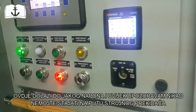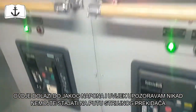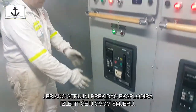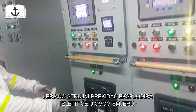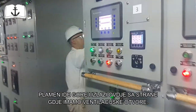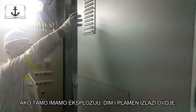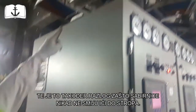And it's a big power here, and I'm telling everybody, never stand in the way of the breaker, because if the breaker explodes, I was on the training, the power is so big that this cube will fly. And you also get flames. Here you have the vents. So if there is an explosion, the flames and the smoke and the energy go over there. And that's why you have space here.